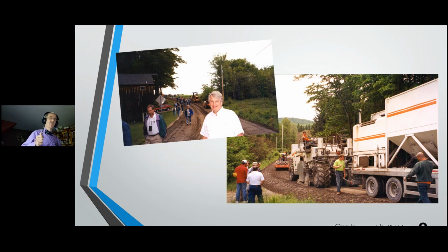But I want to remind you of something. When you're doing stabilization, the biggest rule is don't add any more stabilizer than you need. Extra asphalt, extra cement doesn't help you. In fact, if you add too much cement, the road begins to crack. If you add too much asphalt, you can get little balls of asphalt or asphalt emulsion, and that's not going to be stable. Don't add any extra. If the mix design says 4% or 2 gallons per cubic yard or whatever, go with that. Leave it alone. Don't add extra. That's the temptation we all fall into. It's an easy trap.